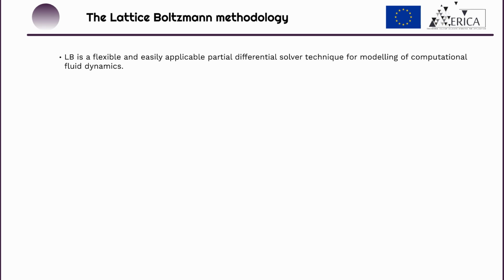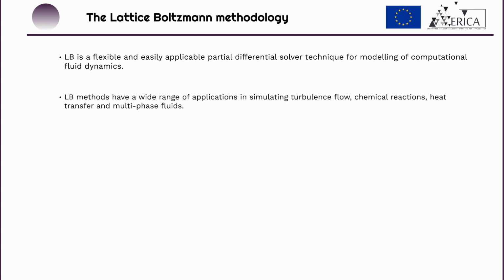To understand the structure of cement-based materials and their behavior during the sorption cycle, it is important to understand fluid flow at the microstructural level. Now, Lattice Boltzmann is a flexible computational fluid dynamics solver that closes the gap between the macroscale and the microscale analysis. It has multiple applications from turbulent flow, chemical reactions, heat transfer, and multiphase fluid analysis.